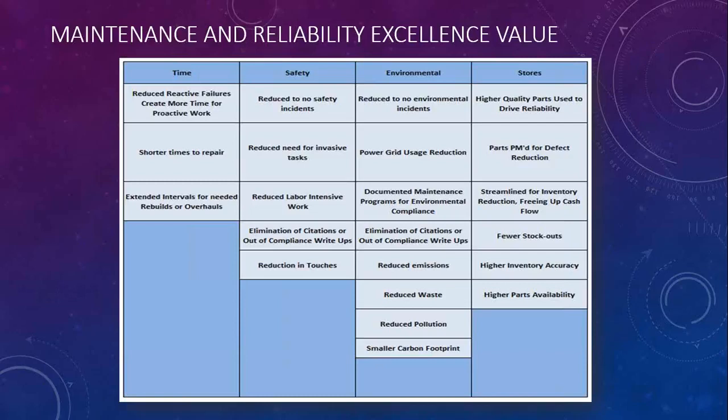But now some folks are asking about on the electrical side, are you using infrared in addition to your ultrasound inspections? Yes. Some of it is obligatory through our insurance company, doing your MCC buckets and some of those types of things. But that's an annual inspection. What we do is we set up routes in our MCC rooms on a monthly basis. We hit certain MCCs, and then if we hear any abnormalities, we tape the bucket with a colored electrical tape, and then we'll come back and suit up and just shoot those buckets that we've identified defects in. So that's kind of the way we do it there.